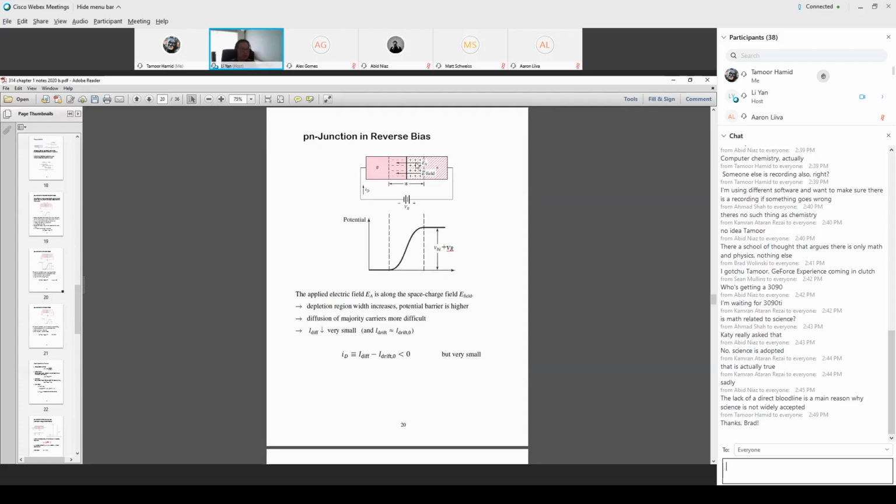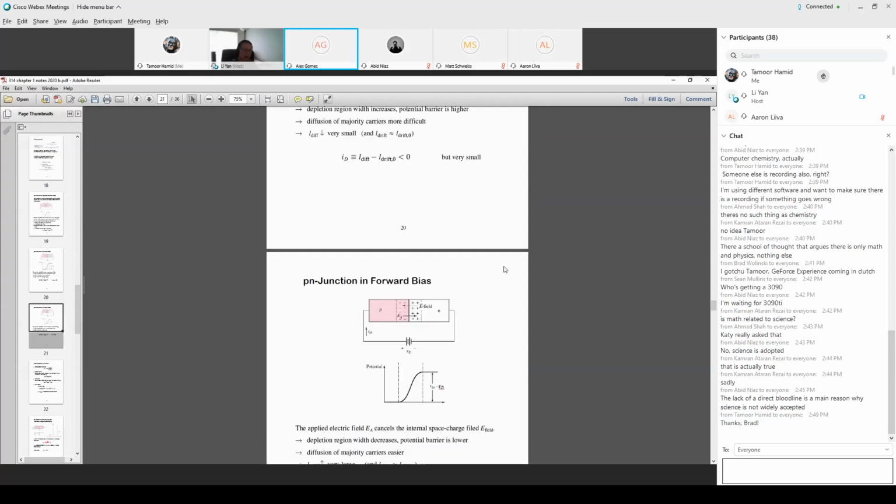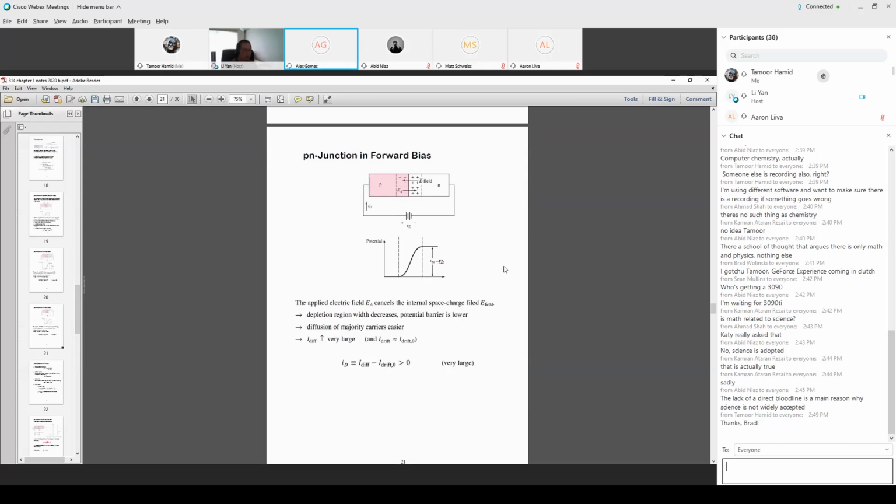You're saying, under reverse bias, the minority carriers get crossed, so you add a little more minority carriers in the N region, is that what you refer to? No, I'm sorry, the forward bias. So that's when the minority carrier concentration increases, after the diffusion process.